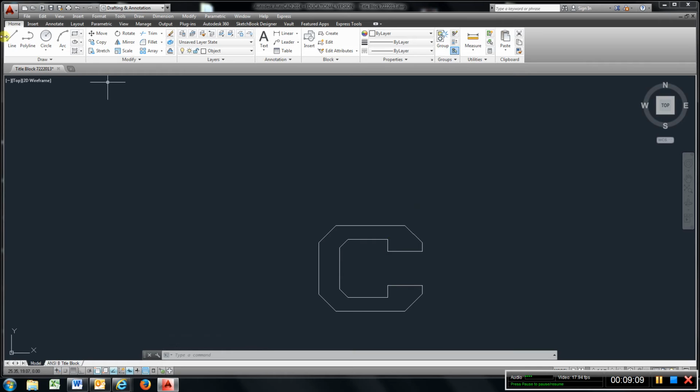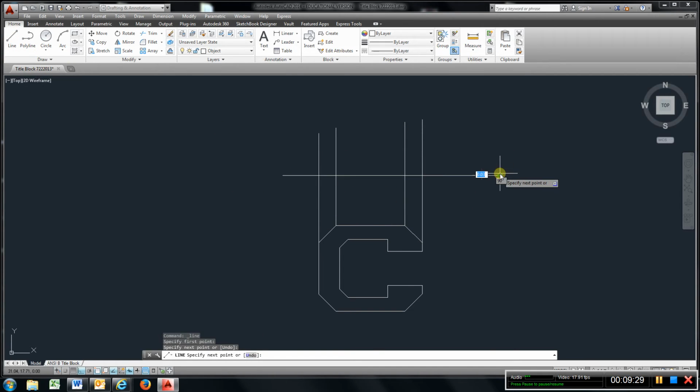Again, come up here, transfer all your points, put on ortho right here. Transfer all your points up. What I'm going to do first is transfer all my visible points up. Up to here, put a line in right here, offset it. I'm going to go 0.25, enter.